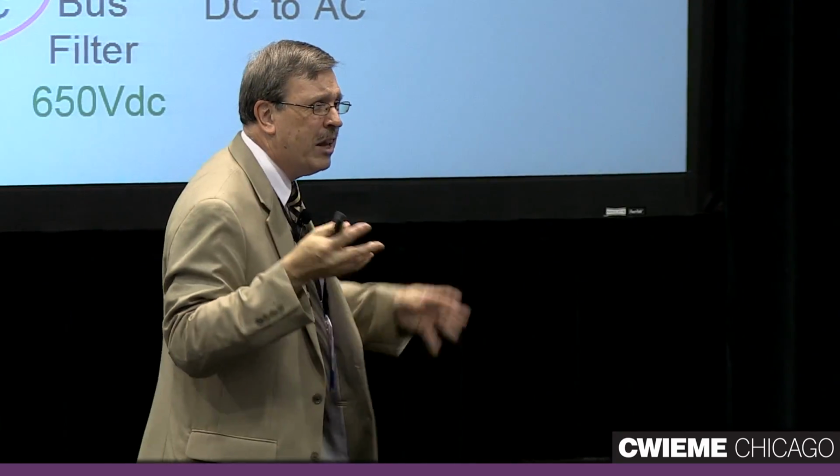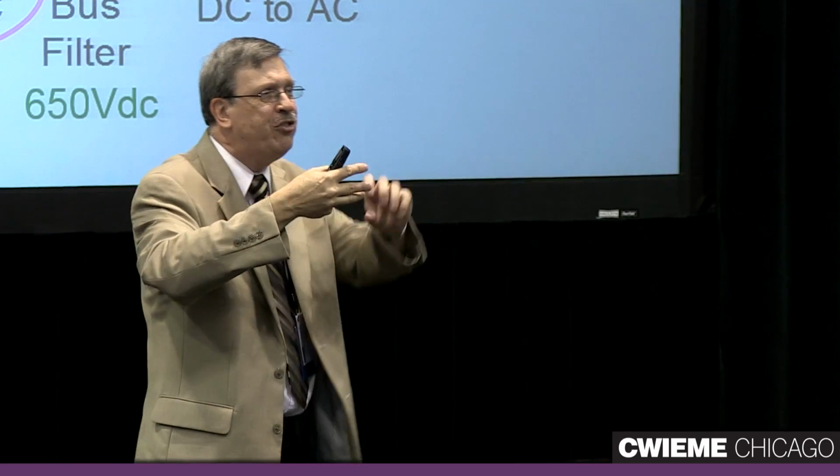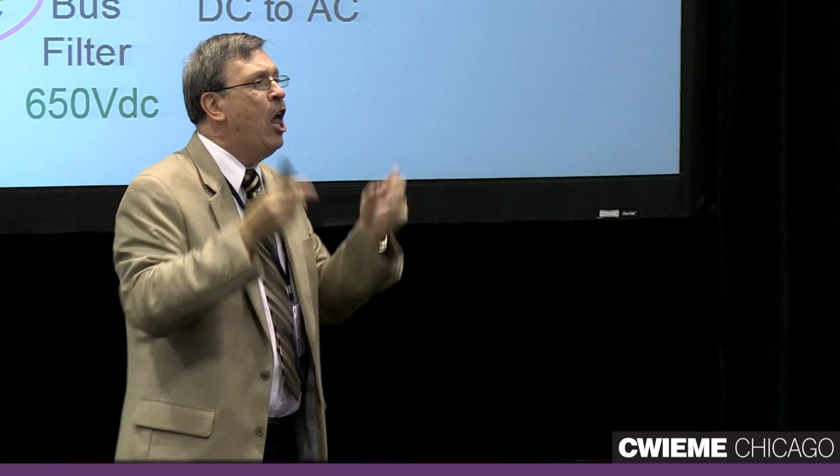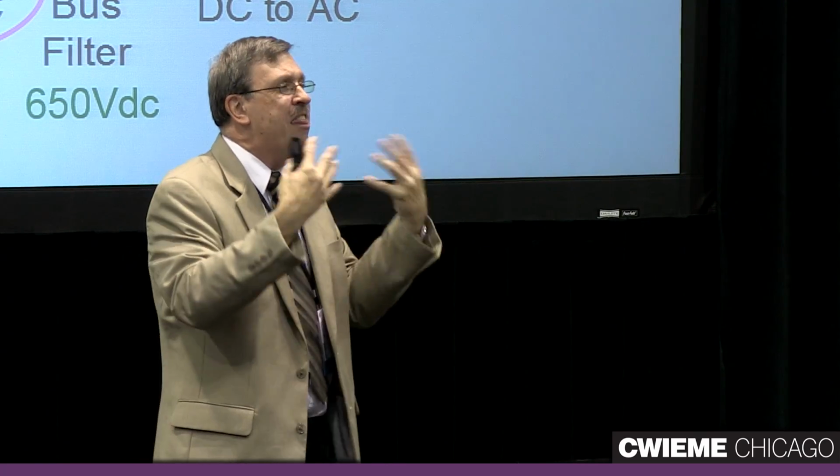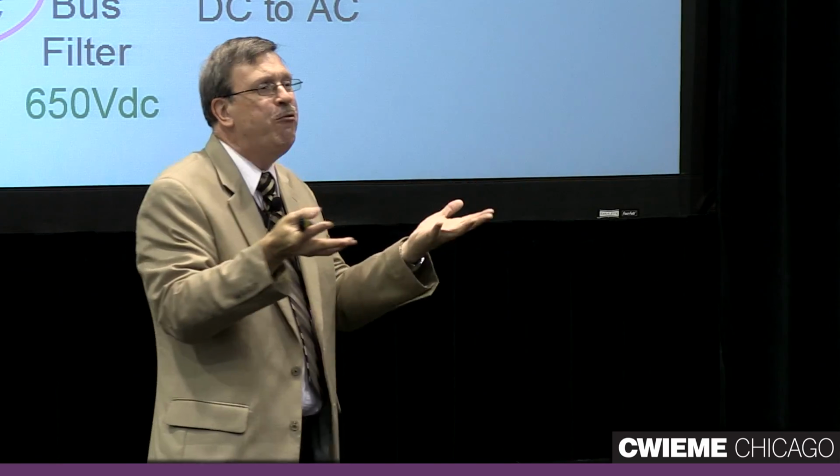So sometimes I get a question, okay, why do drives produce harmonics? I mean, what are you guys thinking, you know? Why do you do that stuff? And the reason why is it's really part of that rectifier section where we take the three-phase AC and we convert it to DC. When we do that conversion, that's when we see a waveform that no longer looks like a sine wave. And when you analyze that waveform, you see that that waveform contains harmonics. So that's really what's going on there.